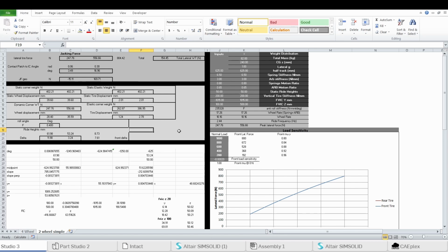It's a common misconception. I've heard, if you make your rear roll center higher than the front, then it has a diagonal weight transfer, taking like weight from the inside left and adding it to the front right, which isn't true. You can't have longitudinal weight transfer without longitudinal acceleration.